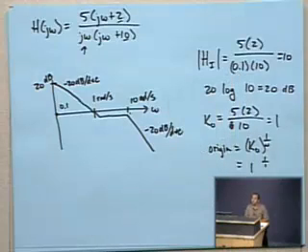If you do decide that that's a meaningful frequency, the stuff from 0 up to 1/10 of a radian per second that's meaningful for me, then evaluate this instead of at 0.1 radians per second, evaluate it at 0.01 radians per second. But it seems like, as people have mentioned, and you guys as well as myself, some of this stuff is really not that important because you're just going to pop this into MATLAB or PSpice and get your results out of it. And secondly, this is just kind of a back of the envelope calculation anyways. So just do the parts that are meaningful to you.